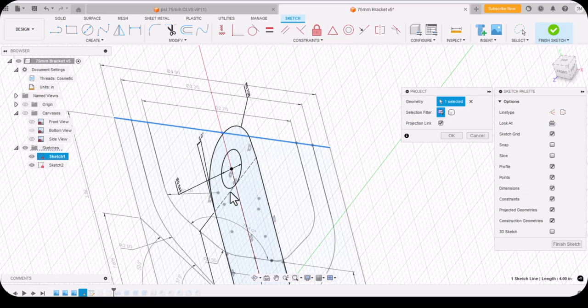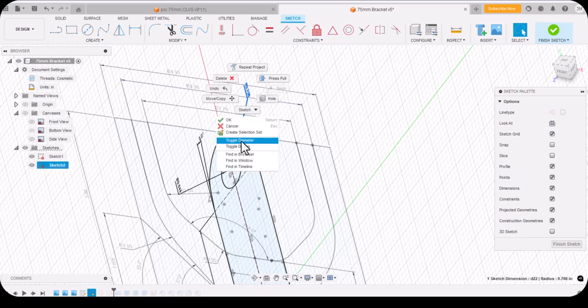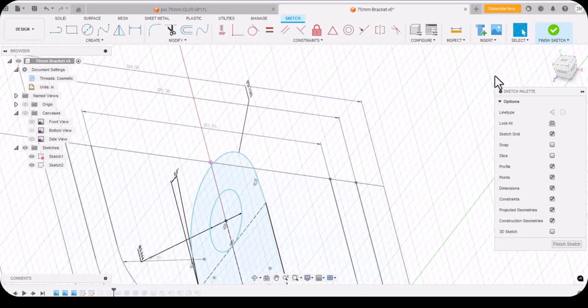Or I could have projected the center line from sketch 1, and I might want to do that instead, because remember we had to add that center line to sketch number 2, and that kind of confused me. I didn't understand why I had to do that because I'd simply forgotten it. But let's go ahead and do that line. So it projects it as a point, and then I'm going to change this radius to a driven dimension instead of a driving dimension. Okay, so now this is a reference dimension, and I'm going to then do coincident between this arc and this point.